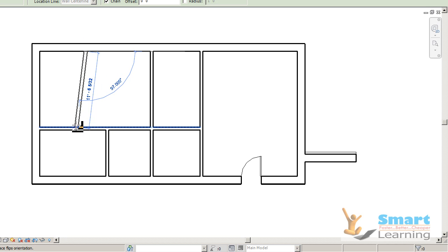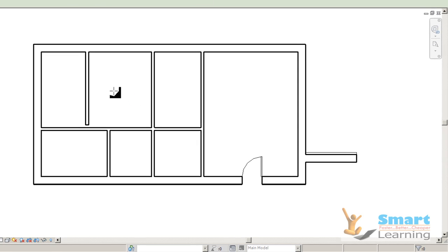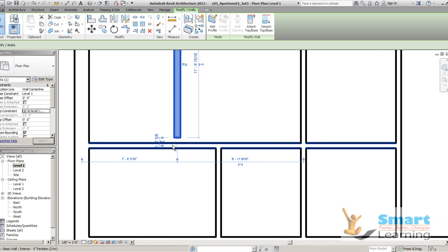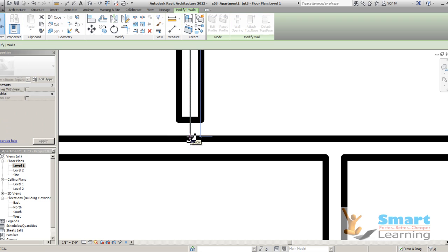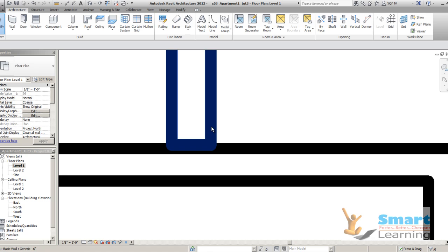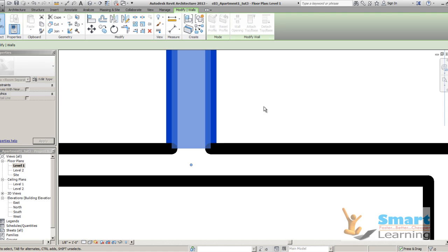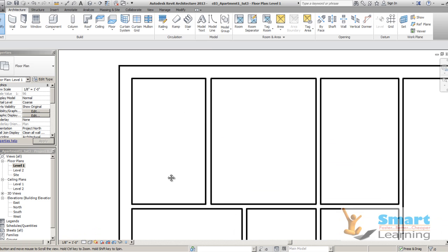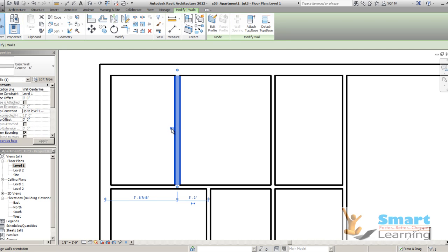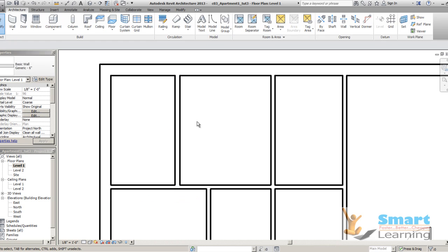Once you create this wall, you can see directly the tracking information that is locked perpendicularly, that is vertically. And I can go to escape. This is not joined here. And once you drag this, you can see automatically this is matching. So still you have to merge this inside. Once you drag this, this will be merged automatically, just like this end. And if you select this, you can flip the directions also. Which side is the inside or outside, that you can control.